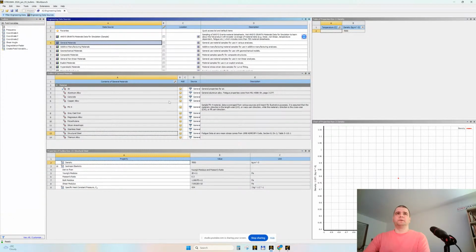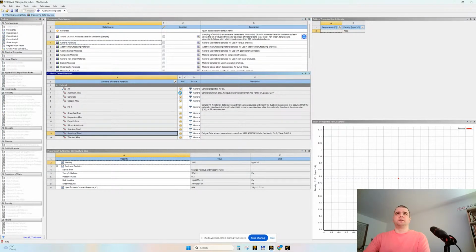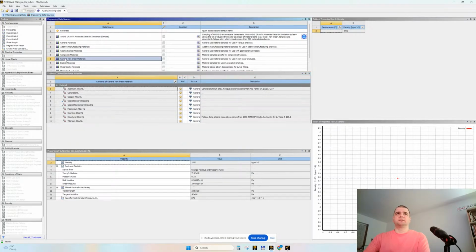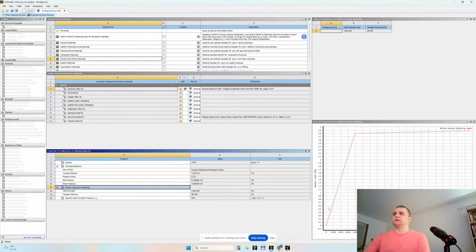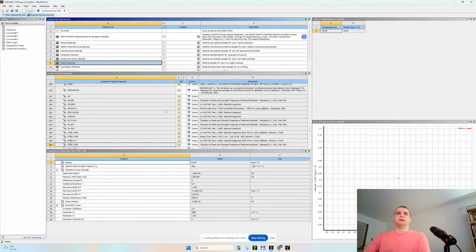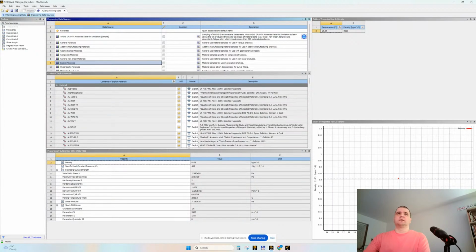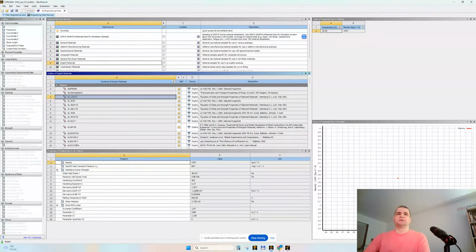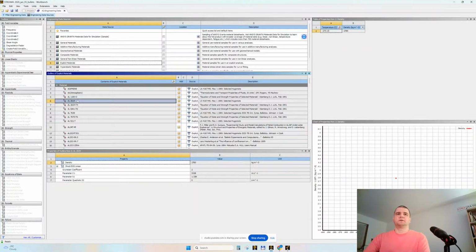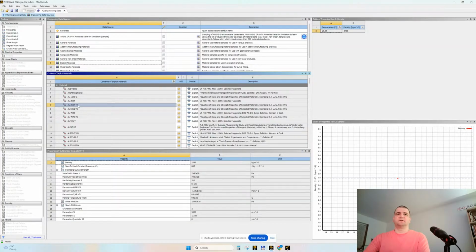we're talking now about the plates, yes? Aluminum alloy, linearly defined, without any plasticity. Aluminum alloy, non-linear definition. Look here. We have here the elastic and plastic domain. And from the explicit materials, let's assign, we have this thing with Steinberg-Guinan strength. This one is very simply defined.